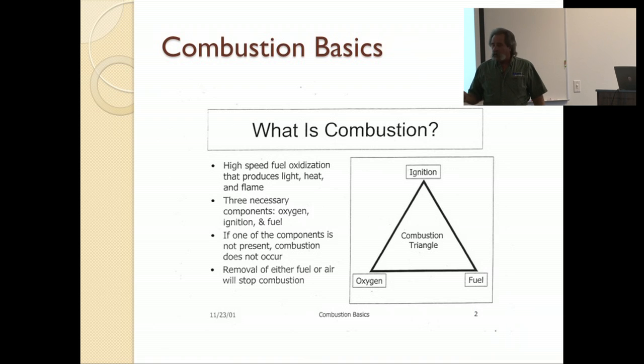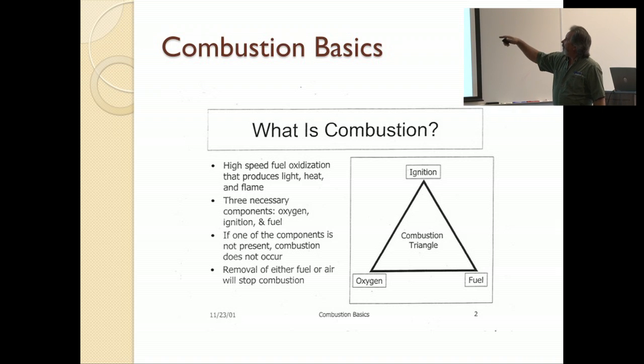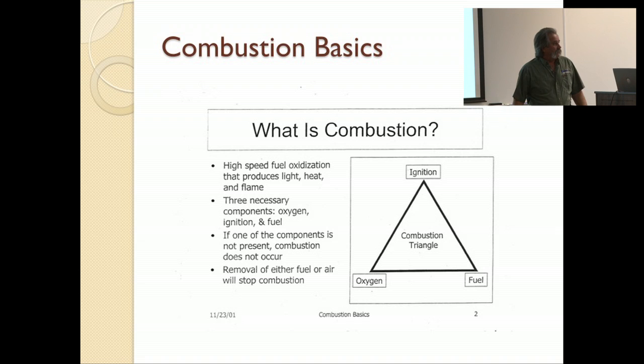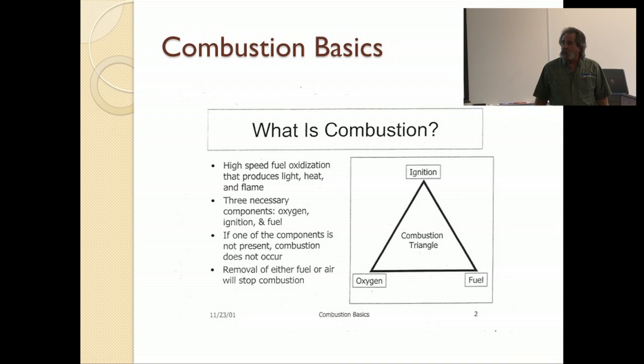One of the things we look for, and we're not going to get into all of those, but as we look at this, if you don't have either ignition, fuel, or oxygen, it's not going to fire. So if you have a boiler that's not firing, one of those three items is missing. That's all it takes. You basically are lighting a match and throwing it on some Kingsford charcoal briquettes. I mean, that's it. It's that simple.